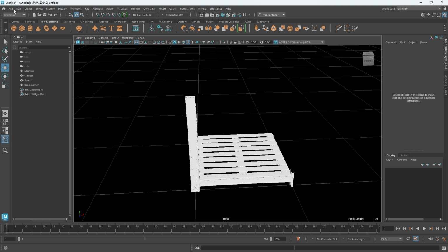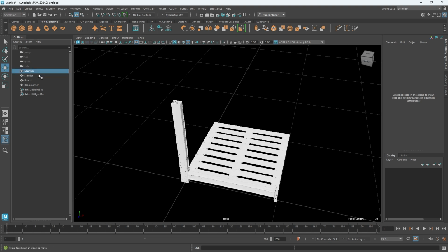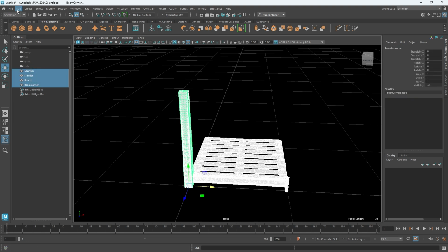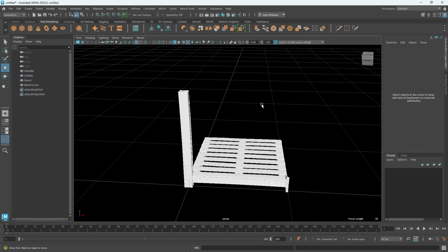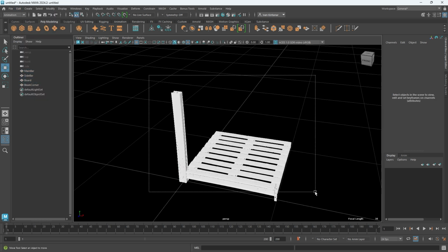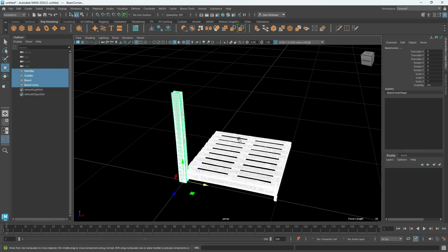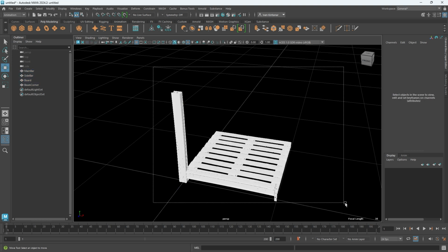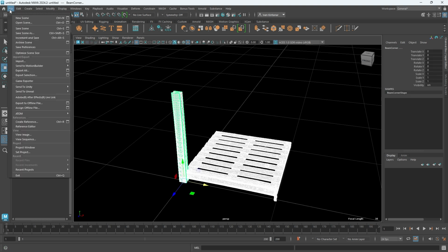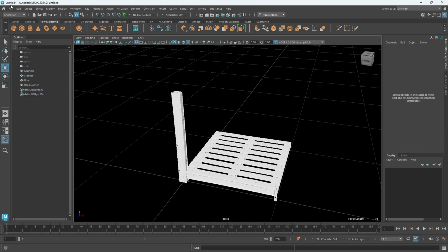But again, we just deleted all of those, we deleted all history. So what I'll do is I'll select all of them, maybe one or two, it doesn't matter. So for this, I want to export all of them. Select all of them. There is a special format called FBX, and that's probably my preferred format for everyone at this stage. So I'm going to go to File.